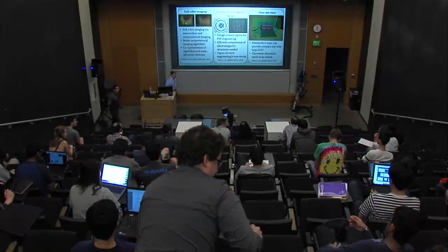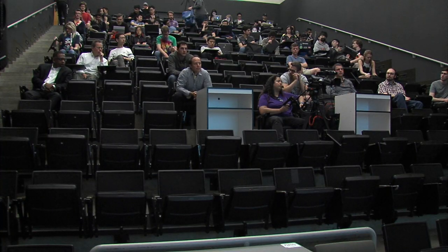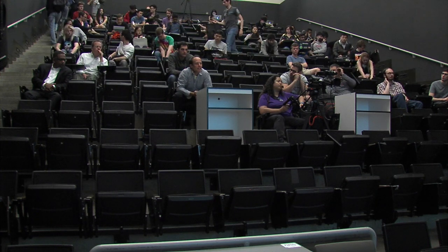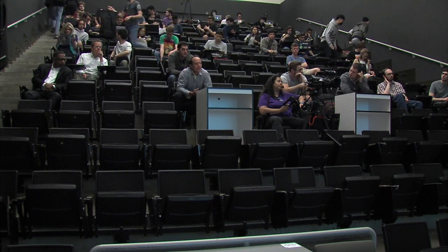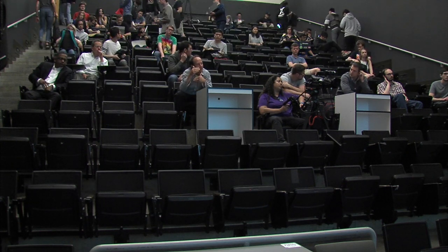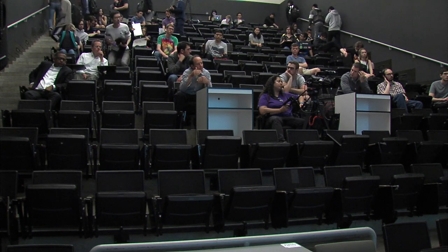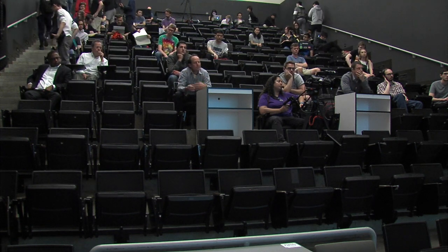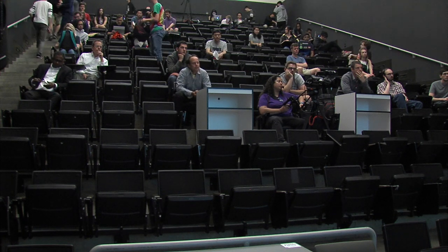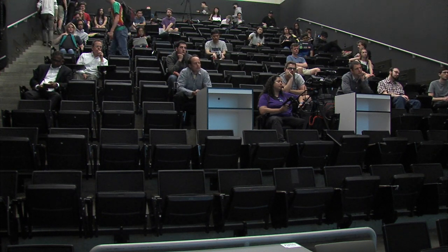Thank you. On the first topic, if you use the extended depth of focus, does that give you some advantages in manufacturing, placing the lens, and have a lot more tolerance from the lens to the sensor, or does the computation vary upon the axial distance? So the question is, when you use the EDOF, do you actually have more tolerance between the gap between the lens and the sensor? And the answer is absolutely yes.